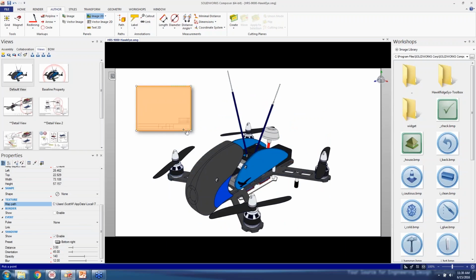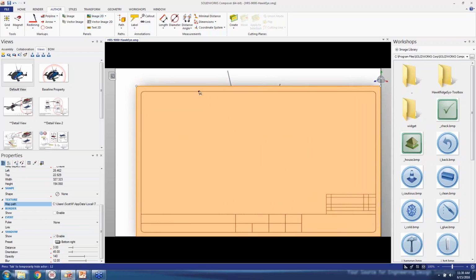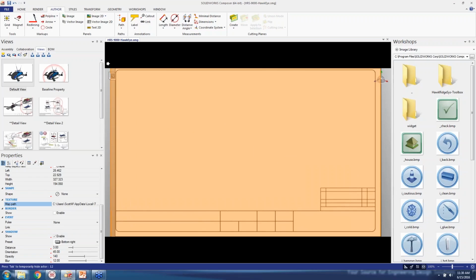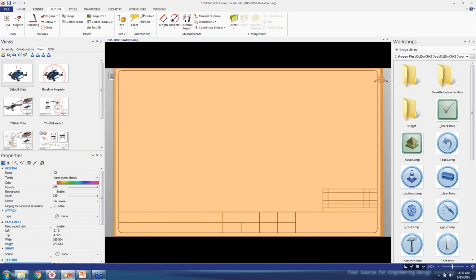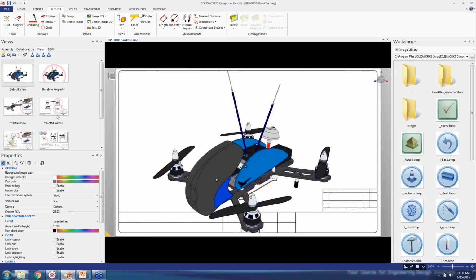Click that guy, open. I could take the shadows off. If you hold down Shift, it's going to scale to the image. If you let go of Shift, you can scale it to however you want to stretch to your viewport, so it's up to you. Once it's there, you right-click. Oh, I'm sorry, that's another program. Once it's there, you say Background Enabled, and then most importantly, you want to set that to freeze. That way you don't accidentally select it.